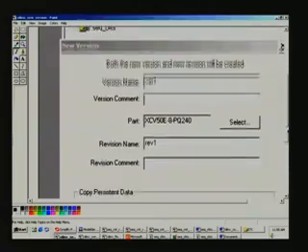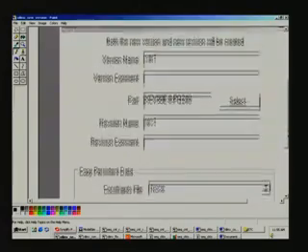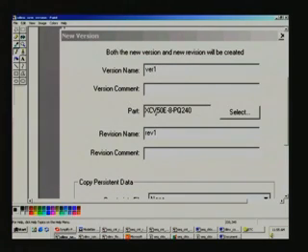And this is the new version window, and here you see the device that has been mapped. Here it is 50E, we can change even at this moment. The input file for this place and route is going to be the sequential circuits .edf file which we created in the synthesis. In fact, we had come directly from the synthesis, therefore you do not have to specifically mention the input file name. It automatically takes the .edf generated in synthesis as the input file here. Although it is showing revision 1 here, I think it is revision 3 that we are going to do.